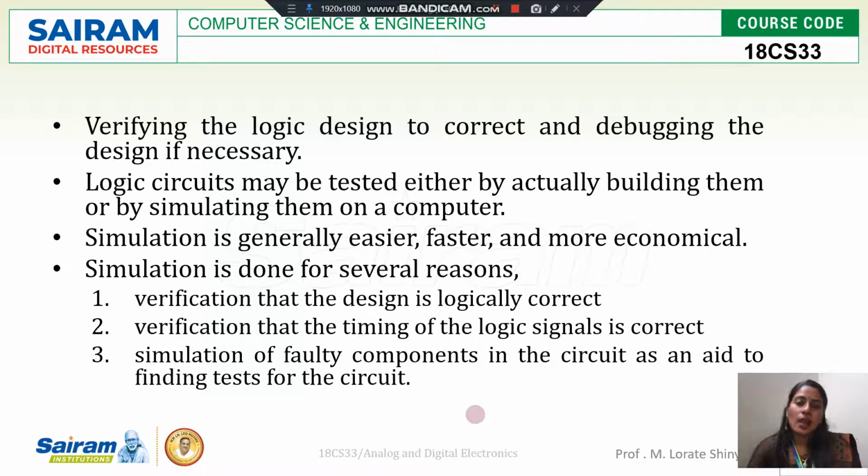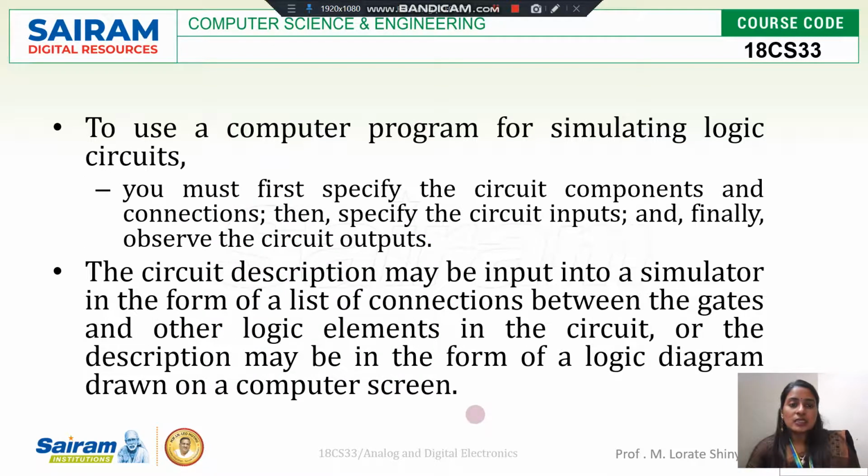There are many advantages also: verification that the design is logically correct, exact timing signals, and simulation of faulty components in the circuit as an aid to finding tests for the circuit. When we use a computer or software for simulating the logic circuit, first we specify the circuit components and connections, then we specify the inputs, and finally we can check the output.